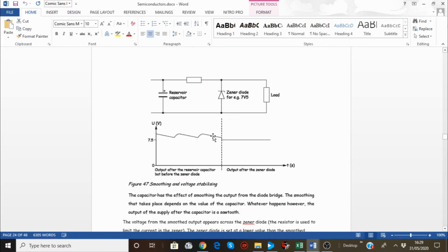So you'll have an effect called ripple effect. So you'll have some sort of a waveform like this. So it's fully charged, discharging into the load, charging again with the next bump, discharging to the load, charging again, discharging. So that's how you get the ripple effect. Now we've got from the full AC to full wave rectification, and then to this ripple effect DC. Now we want to convert it to a full fixed DC.